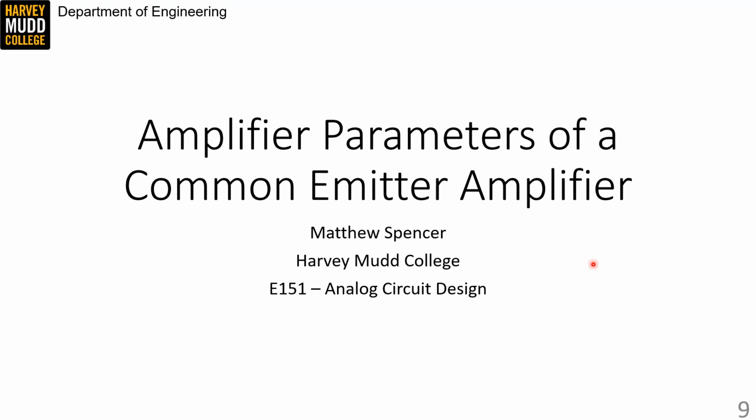In this video, we're going to apply our new amplifier model to the common emitter amplifier. This will give us expressions for Rin, Rout, and AV that we can use whenever we see a common emitter. However, we're going to make one really important decision about our biasing network when we do the analysis for these Rin, Rout, and AV expressions. That will help us generalize these expressions to a wide variety of biasing circuits.